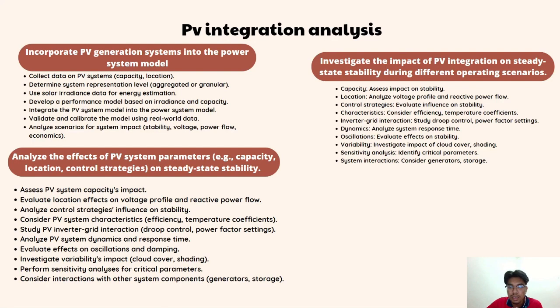This involves assessing PV penetration levels and their effects on system stability, analyzing voltage profiles and potential deviations, evaluating power flow and line loading, studying the interaction between PV inverters and the grid, investigating the impact of PV generation variability on system frequency stability, analyzing the need for reactive power compensation devices, and assessing system oscillation and damping characteristics by considering various scenarios.